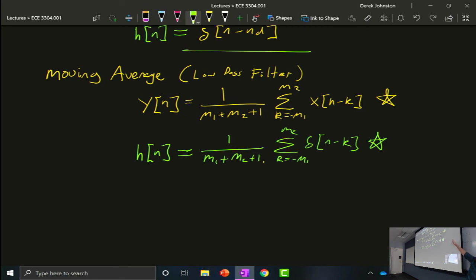And it doesn't seem like that much math for something that's really simple, like this moving average thing, but we're going to do some sophisticated stuff. And to do that sophisticated stuff, it requires tons and tons and tons of computations. Whereas instead, all we have to do is calculate our impulse response, get that one array that has our impulse response, and then just hit it with convolution, and we're done. Like I said, it drastically reduces the computational load of what we want to accomplish.